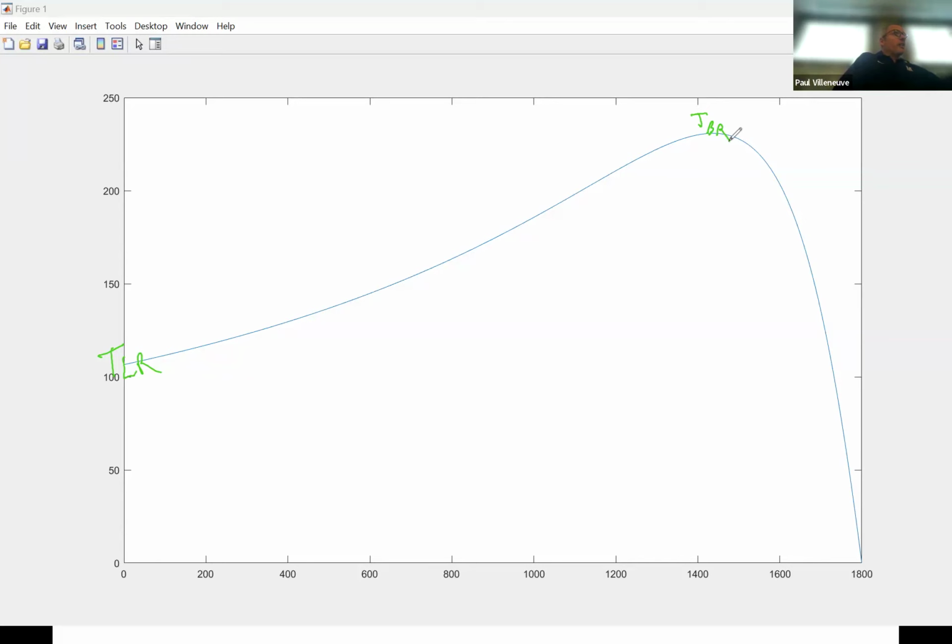We tried to tweak it, and then all of a sudden, it just would run at a very low speed. Theoretically, if it was possible, it would actually stop, but the torque started to change a little bit. And so that's why with those dynamometers, we weren't able to get it. But if we could maintain a constant torque, the motor would have stopped in place. And then we'd have to shut the breakers off because the motors burn up very quickly when they're running at locked rotor conditions.